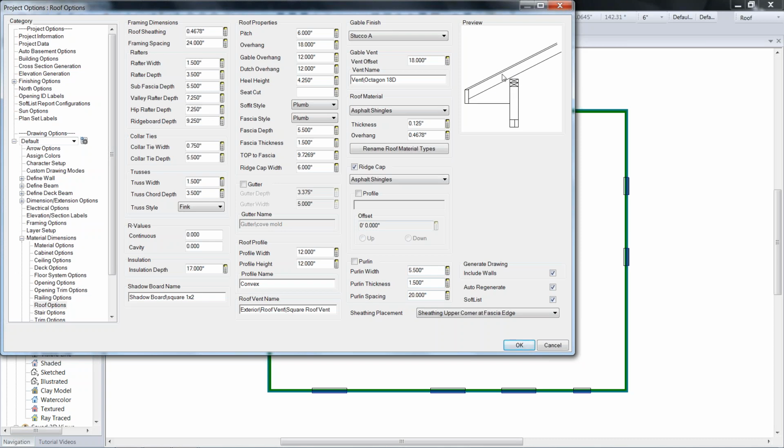I'm not going to add an energy heel. I probably should, in today's day and age, with HERS ratings especially. We could change the heel height if we wanted to. If you wanted to do that, just come over to this heel. If I wanted to add a 6-inch heel to that, I would simply say the new heel height is 10.25 inches, and I've given you a heel, and that's going to help my energy efficiency.